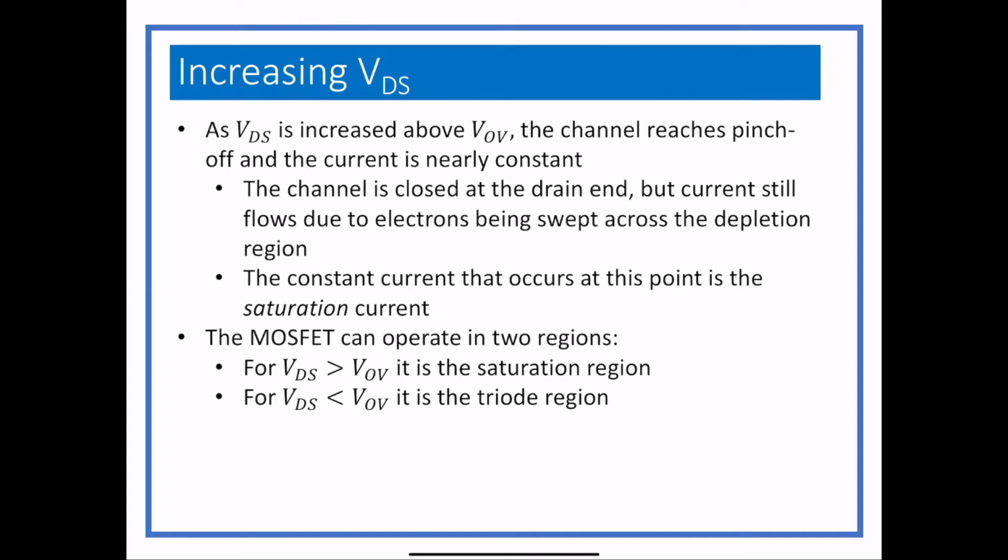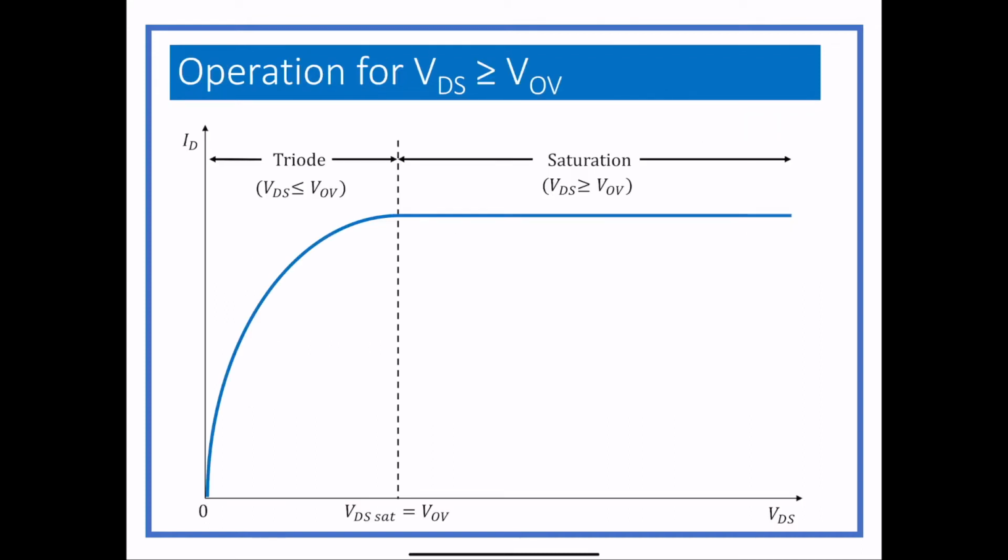So if we look at this graphically, there are two distinct regions of operation. We have right at the bottom where 0 is, where there's an almost linear relationship between VDS and ID, which means that if we come up with an equation to describe that, I'm not going to derive it, but I am going to tell you what it is, VDS will appear in that equation because it actually affects that curve.